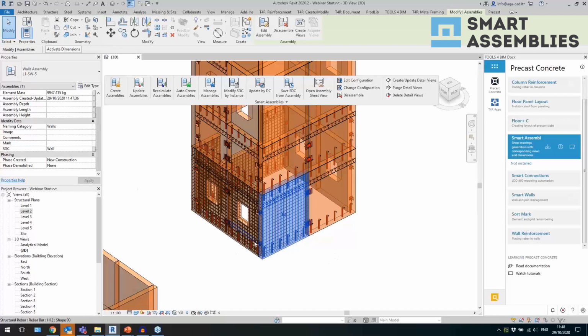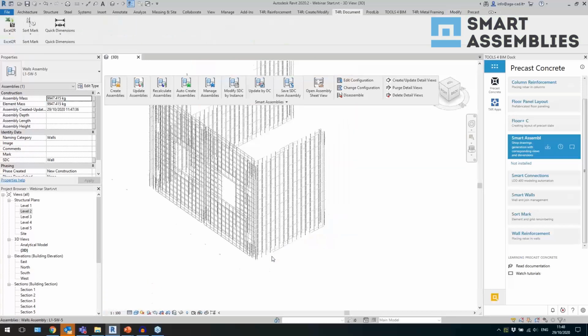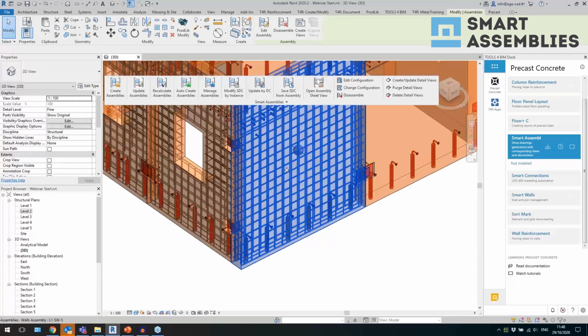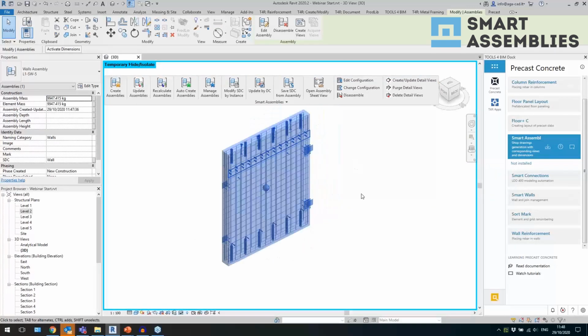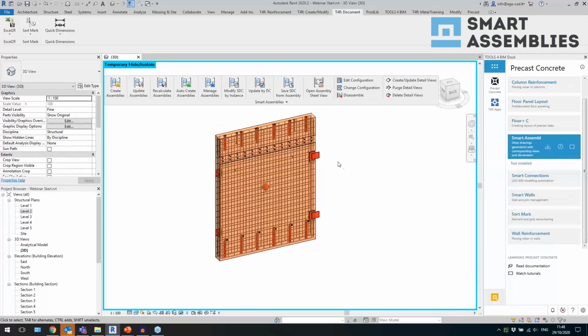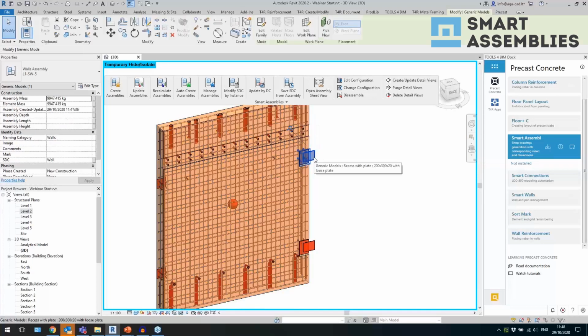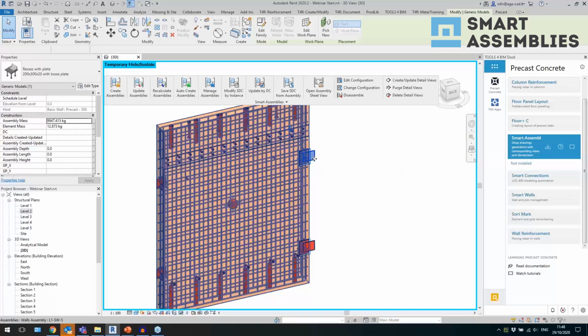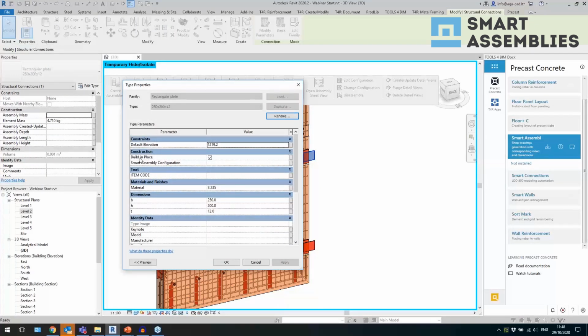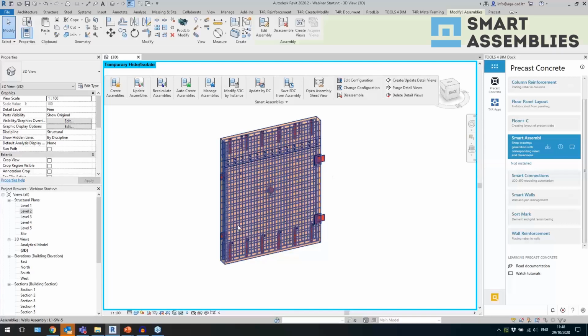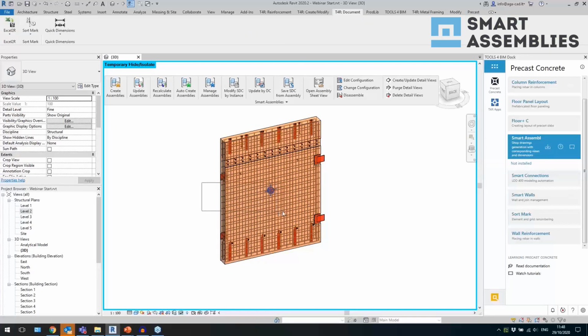All right, so this is the assembly created. You'll see I have element assembly mass. It calculated this based on the materials and the solids which are available in my assembly. These plates have nested families like this one. But if I add a special parameter like build in place, this plate will not be added to the assembly, so I will not have it in my drawing. This is the gravity point also inserted.